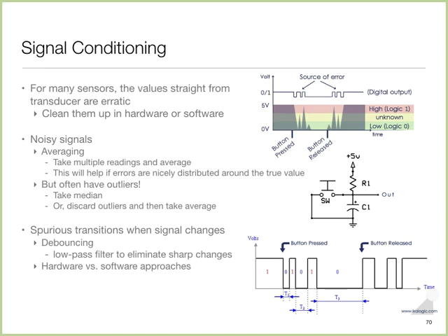First, a lot of effort goes into cleaning up the signals right at the sensor. Transducers tend to be kind of noisy, so there's a lot of effort at the circuit level to clean things up, average them out, calibrate them, stuff like that. I'm sure you would have seen these things. Even simple stuff like switches are subjected to debouncing circuits.